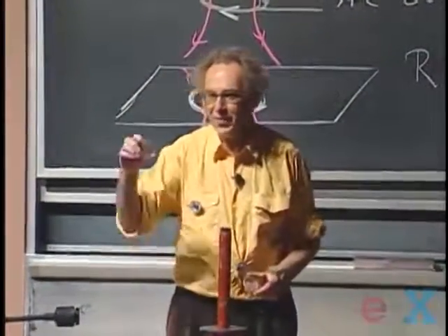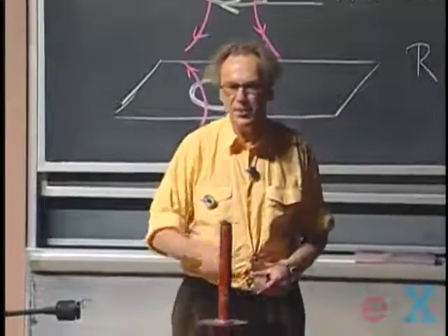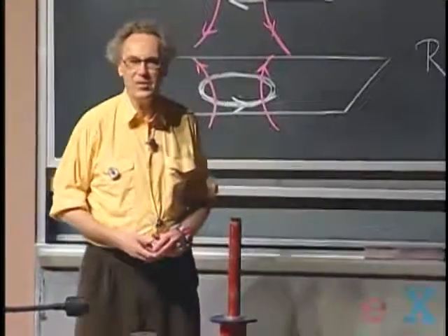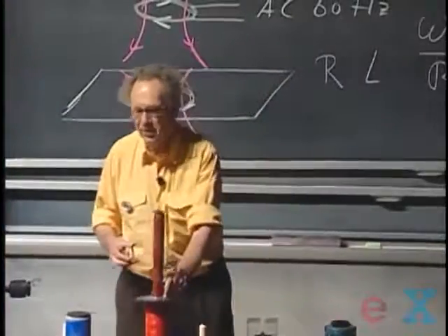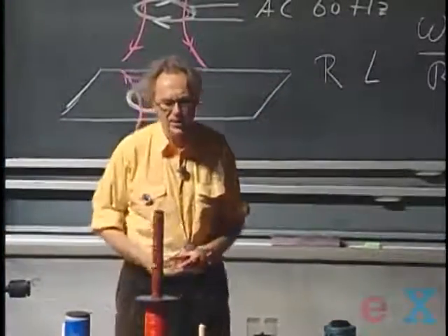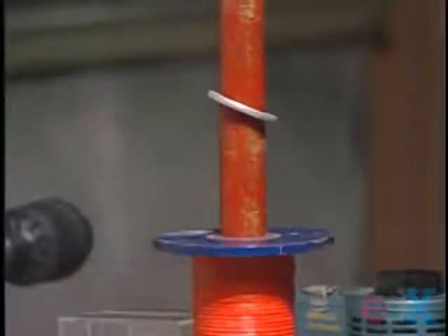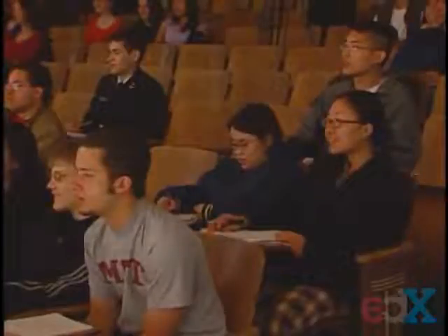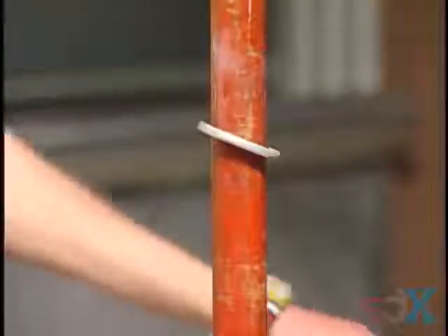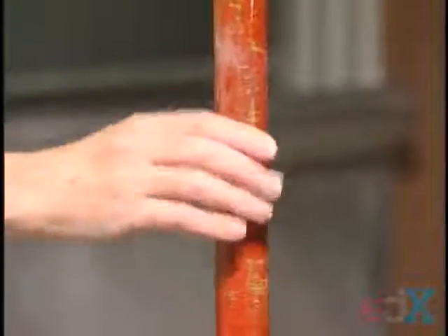Half the time it attracts, half the time it repels. That means nothing happens. No magnetic levitation. Same EMF, same self-inductance, but an infinite resistance, and here you see magnetic levitation. Since the induced current in the ring is extremely small because of its very high resistance, the force on the ring, whether it's repelling or attracting, in any case, is practically zero. So that alone is enough reason for the ring not to move at all.